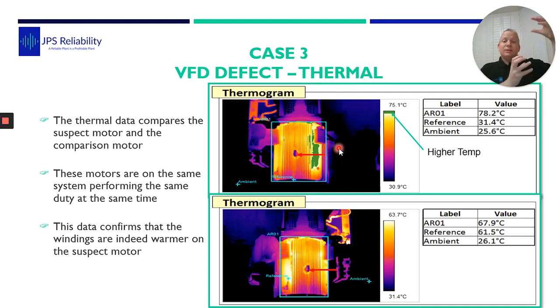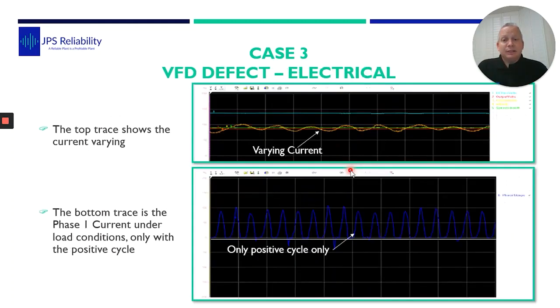And part of that data, it's a 4-pole motor, says 4 north and south, so 4 sort of coil packs. Well, one of them was warmer, so we're thinking we've got an electrical defect. Some are getting warmer, and the vibration was telling us that there's a different pulse, different electrical motion. So from that, the chap did an electrical investigation, and this is what he actually found.